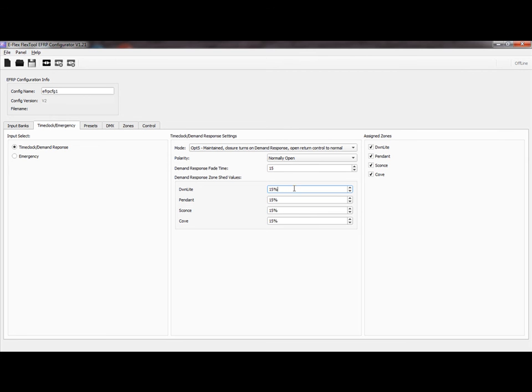The eFlex relay panel provides the capability to configure the reduced power on a zone-by-zone basis for maximum flexibility in reducing the total maximum power in a space. A spin box is provided for each zone to adjust the load shed value from 10 to 40%. The default value is 15%. This 15% value meets the California Title 24 applications.